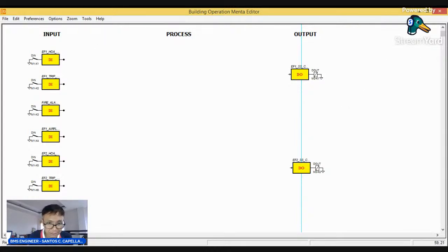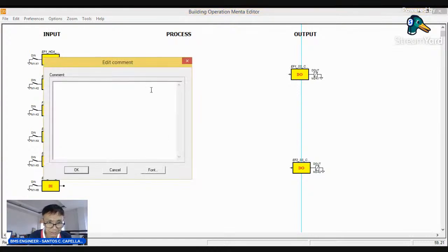Okay, let me make a comment here. Duty standby operation, and when duty fan trips, then standby fan will kick in.